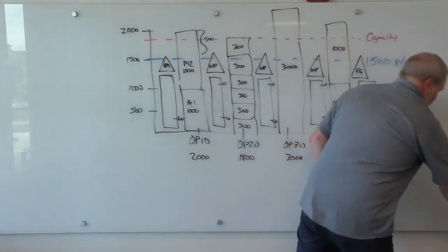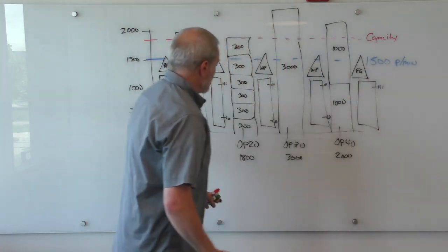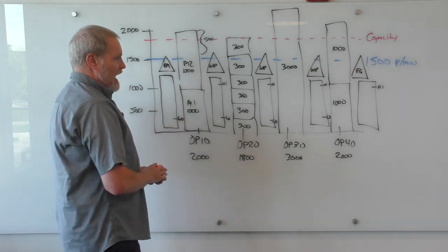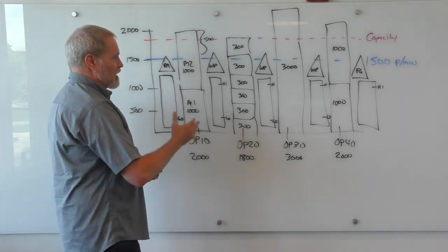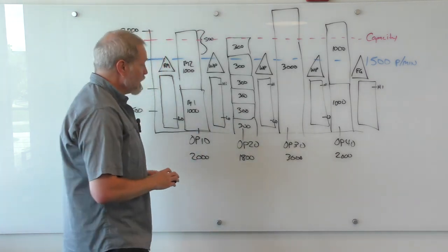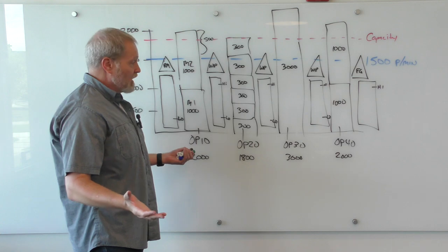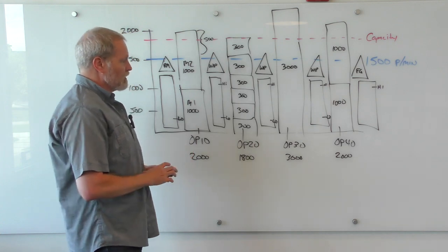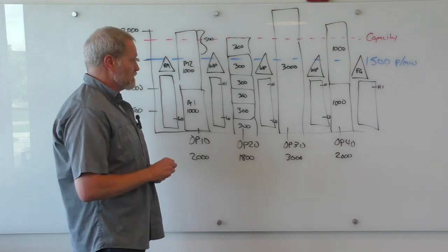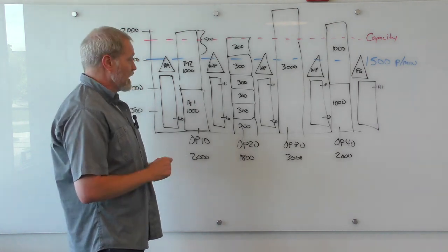So each of these inventory levels needs to be sized based on typical outages within the process that allow the rest of the machines or operations to continue to flow. That calculation can be complex, and it is an important part of bottleneck analysis, but it's also a big part of designing the line to flow properly.